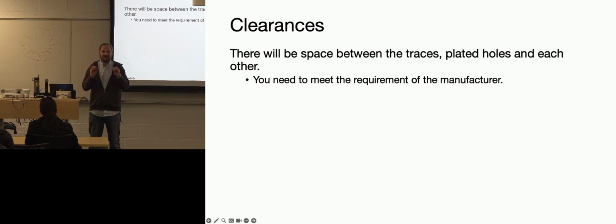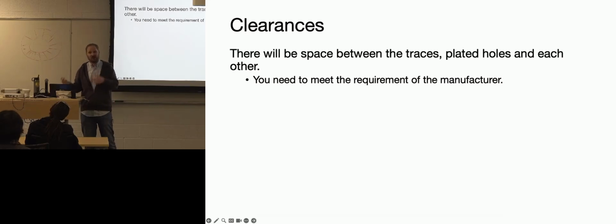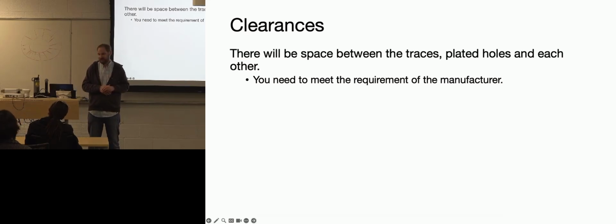So I have definitely personally made the mistake of designing a board that could not be manufactured because I didn't put the design rules in. Now, thankfully, I wasn't that far off, but I had to go and redo some of my design and move things out because the manufacturer we ended up going with couldn't support my design files.